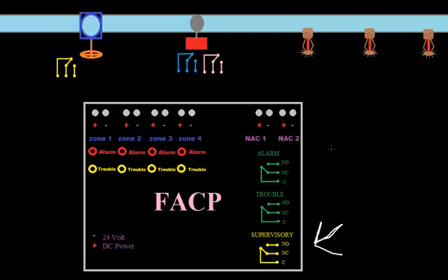So one thing that can be confusing for newer technicians or people that are new to fire alarms in general is the difference between supervisory and supervising a circuit. We've talked about end-of-line resistors, right? When we have smoke detectors or heat detectors at the end of the circuits, we had a resistor, and that was to supervise the circuit. So if it were open, we'd know that it was open, right? I mean, the panel's designed to know how much current should be flowing through a circuit, and if there's an open circuit, it causes a trouble, and that's called supervising.